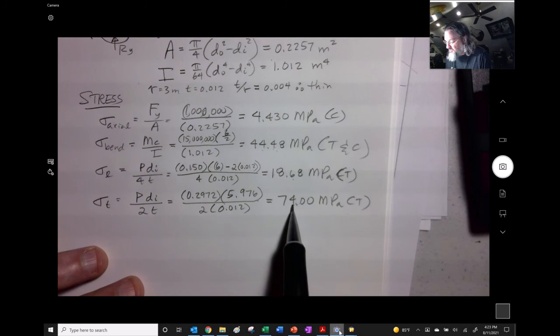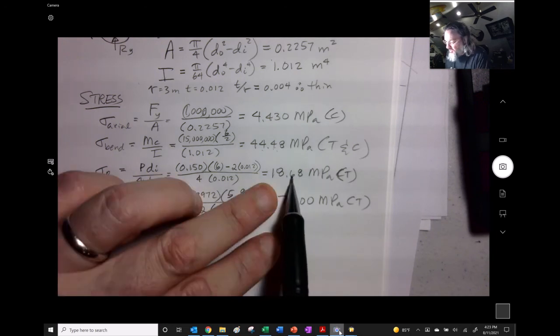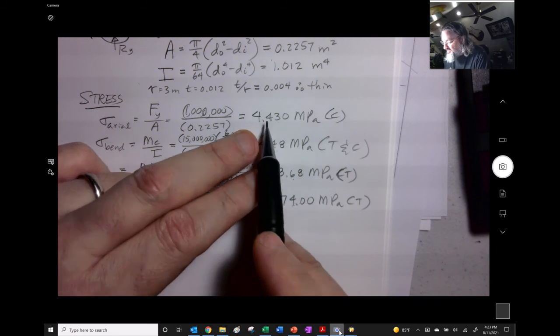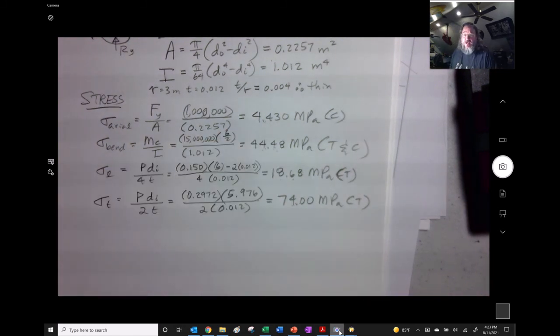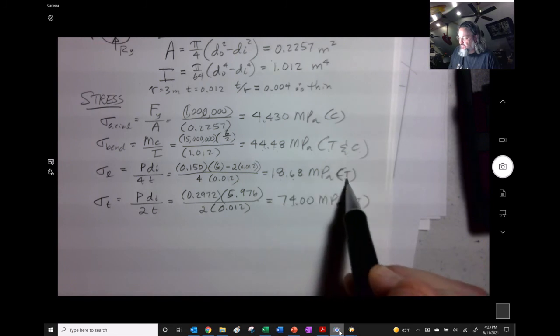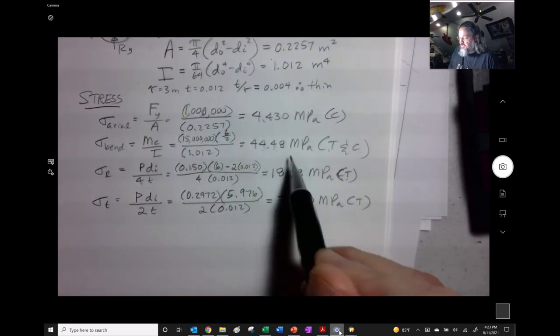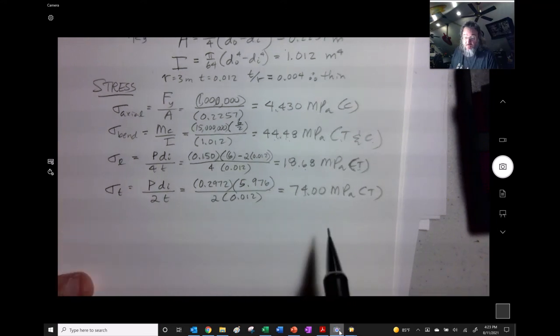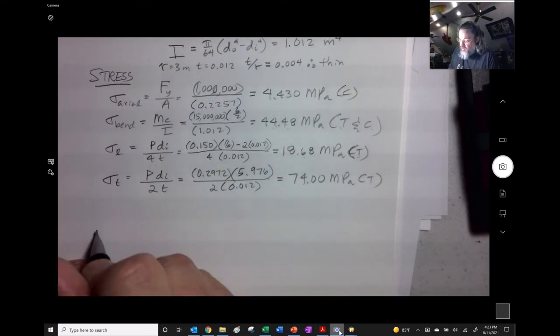We're going to take the tension side of this and the tension side of that and subtract out the compression of that, right? Because we could have used either the tension or compression, but this is going to be significant enough that it's going to be the worst magnitude of stresses, which is really what we want to have.